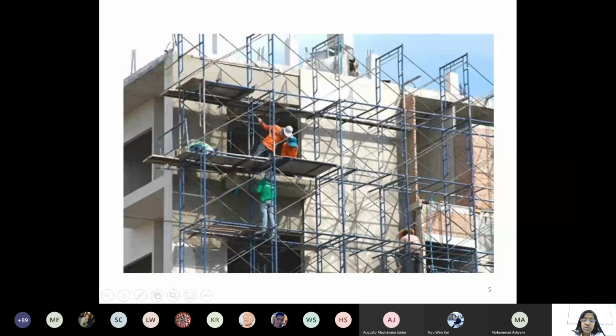Here you are seeing, all the blue lines are called formwork, because the building is being raised and the people have to reach the top to do their components. One by one they have to build their walls, columns to be extended, beams have to be cast, and so on, right? These temporary structures might be steel or wood, but mostly steel because of high rise; it has to withstand the loading. So they use steel rods, steel pipes, steel columns and beams to construct this with the toe board. We'll see one by one.